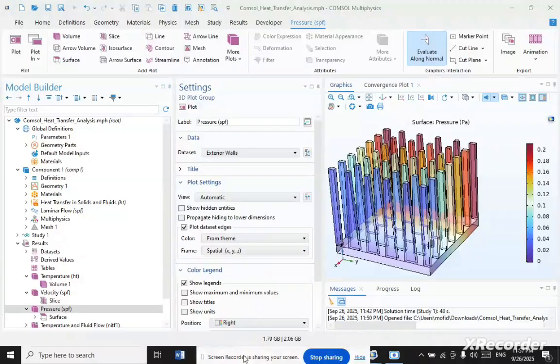Earlier, forced or natural air cooling using conventional pin fins was enough as heat flux dissipation was very low. However, with the increase in heat generation, these devices cannot fulfill the demand. In addition, these devices are bulky and loud, so researchers started focusing on liquid working fluid, as liquid has higher thermal conductivity than air and comparatively offers up to 10 times increase in heat transfer rate.